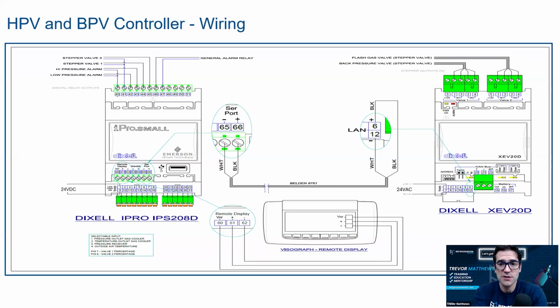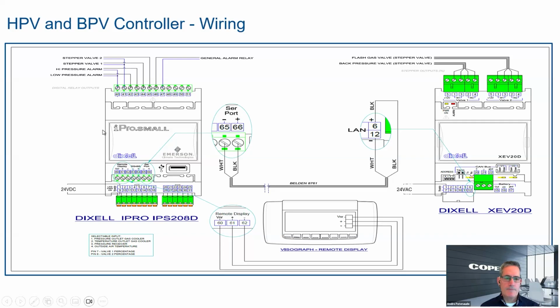But this is a test as a technician. You go out there and you've got to get your meter out on this stuff. Am I actually getting voltage out to that valve? Because the valve is moving or not. So that's just a tip there.